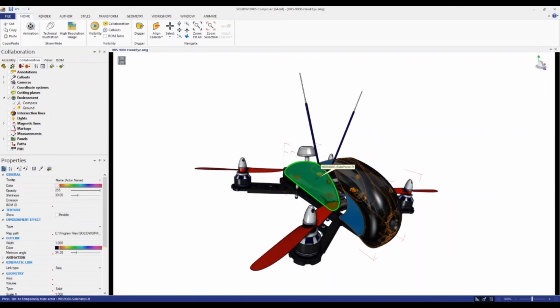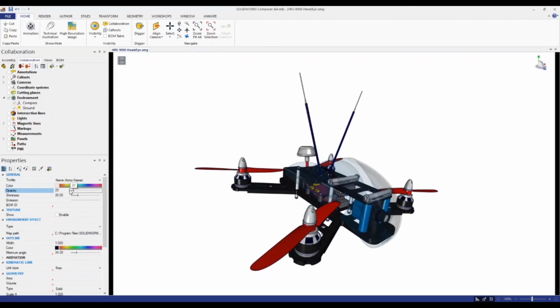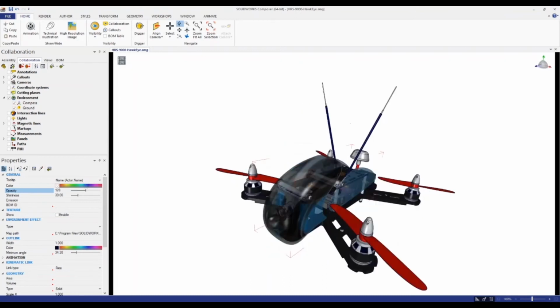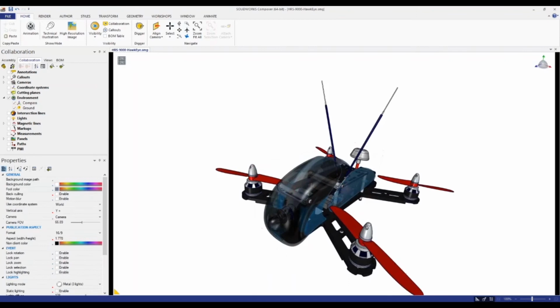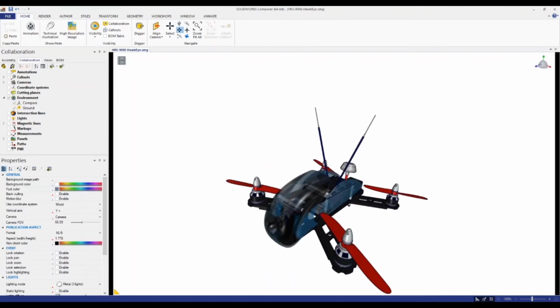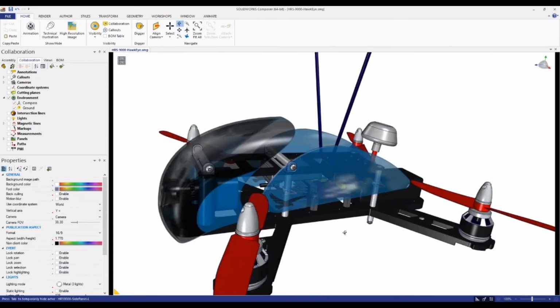You can select the component, your actors, and then over here on the left-hand side, we're taking a look at opacity. So I can turn this down, right? I can go so far as just having it pretty much all hidden, which is an opacity of 0. Or I can go maybe halfway, about to a 128. That still preserves the components, but then if I look close enough, I can see the insides.